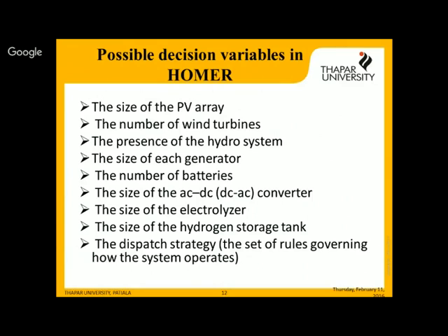If I'm investing 1 lakh rupees in a system for 20 years, obviously I will charge the interest, and after that I'm going to calculate the cost of energy. In the meantime, suppose 5 replacements are required, so I'm going to calculate that value. Today's battery cost is 10,000, and after 4 years the battery cost will be, let's say, 15,000. What will be the value of 15,000 in terms of today?